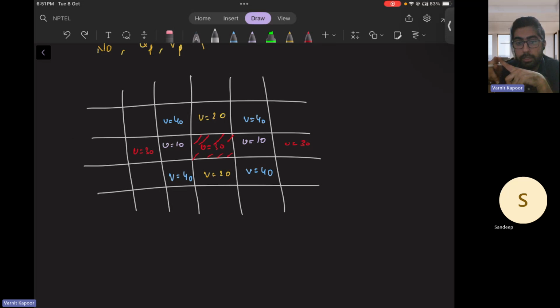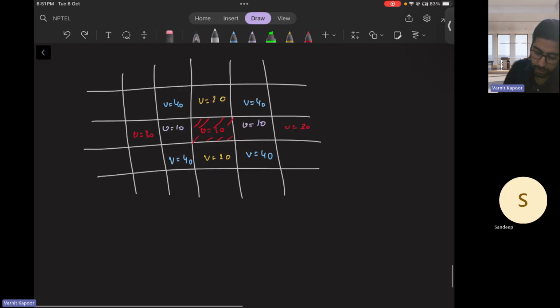But what about the momentum equation? If the momentum equation sustains this pattern, then final u and v will contain checkerboarding. As well as that, P is also unknown to us, if you remember. Both P and u, v are unknown. If you recall our equation, this is something like a checkerboard scenario.